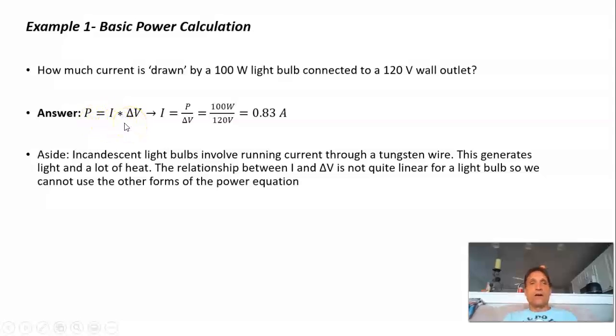If you have a 400 watt something hooked up at 120 volts, you should know that's consuming 3 amps. So you should be able to figure out how to keep your current under what the breaker is going to trip. So that's why these calculations are practically important.